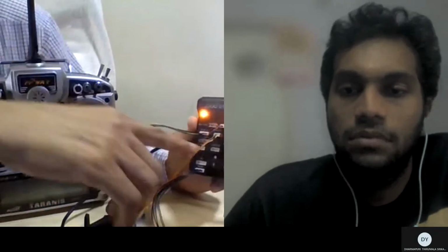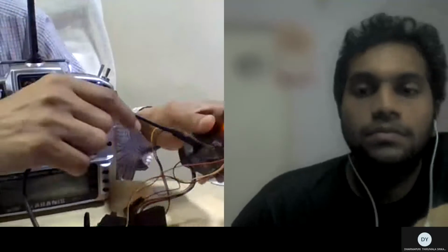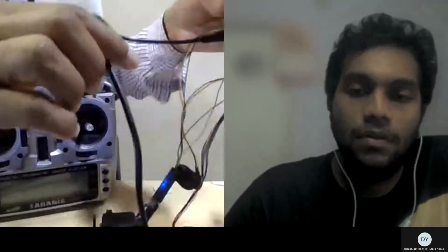Then I told you there is a power module. You should connect the power module with this type of autopilot system. And then others are also there. You have ADC, then you have another I2C connection, CAN bus, USB, SPI. So it depends on what type of sensors or hardware interfacing with this electronics or autopilot system you're using. Okay, so you should check what communication protocols are there. Okay, if there is a camera, you can also interface the camera. Okay, so this is the basics.